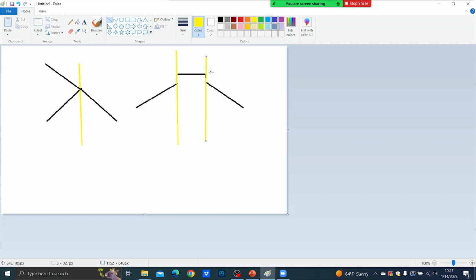Again, there is something called wider median and narrow median. In our roads in Sri Lanka, we have narrow medians. If it is a narrow median, we don't have an axis of rotation like this. Instead, we take the center line as the axis of rotation. Even though there is a center median, we rotate along this center line.